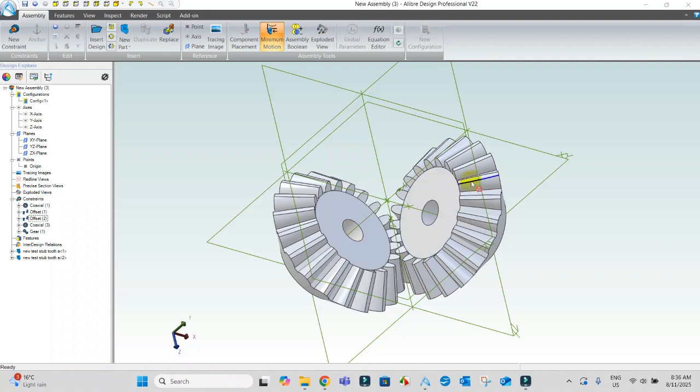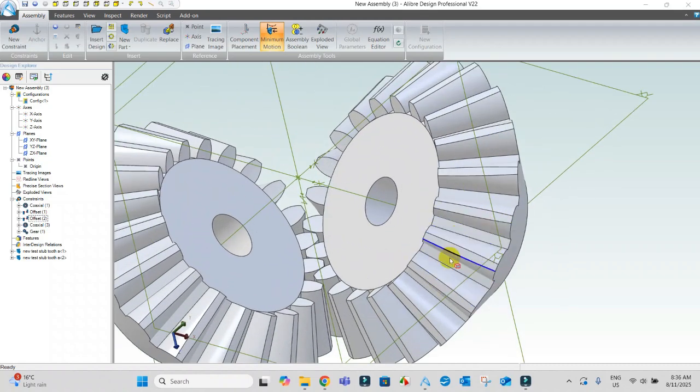I did the other day about profile shifted bevel gears. What I've done is come up with a slight modification of what I did the other day. You see here we've got what looks like slightly wider teeth and a slightly different form. Oddly enough, this is made with the same cutter, but if you approach it slightly differently, it has a different result.